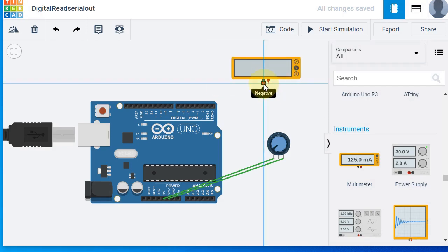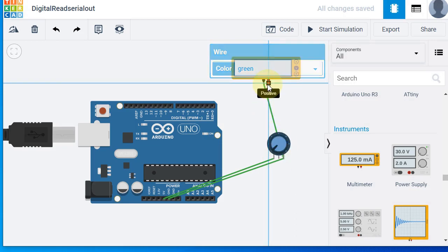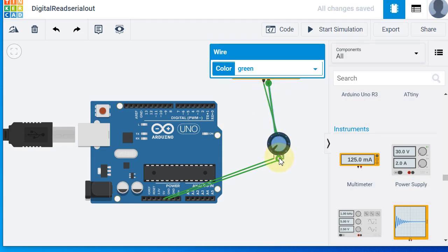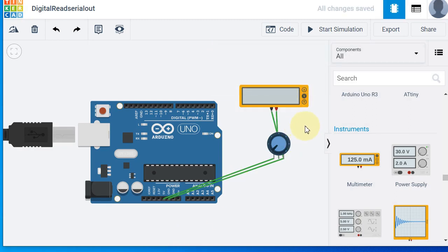So I make this multimeter a voltmeter. I'm going to connect the negative. Already the negative is connected to this terminal 2. So I'm going to connect this terminal 2, and on the wiper I want to measure the voltage. How the wiper varies my voltage, and how I can give this wiper variation as my analog signal. Without writing any code or connecting any other connections, I just want to measure the analog input. For that, I connected a simple circuit and start the simulation.